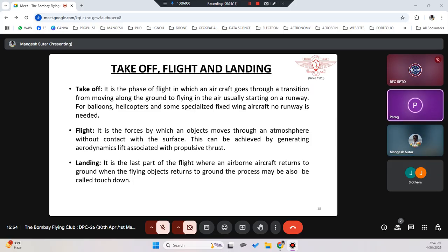The start of it. I am saying when you are actually trying to take off, you need to do the pre-takeoff checklist. You need to see certain parameters. First, you have to see if any warning or notification is there. Sometimes there is a GPS malfunction, or compass calibration is not proper, or some kind of errors would be there. You need to see that there are no errors, so your takeoff is error free.